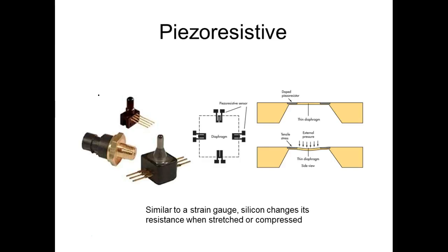Usually we use, for years and years and years, all the logic that we did was done with electromechanical devices called relays. You're all familiar with relays. The problem with these devices is that they have moving parts, they're electromechanical, which means what? Now they have two ways they can fail, right? And of course they're going to be slower because of the mechanics. So they came up with methods they could do this electronically, with solid state or semiconductor devices. And originally solid state started off with vacuum tubes.